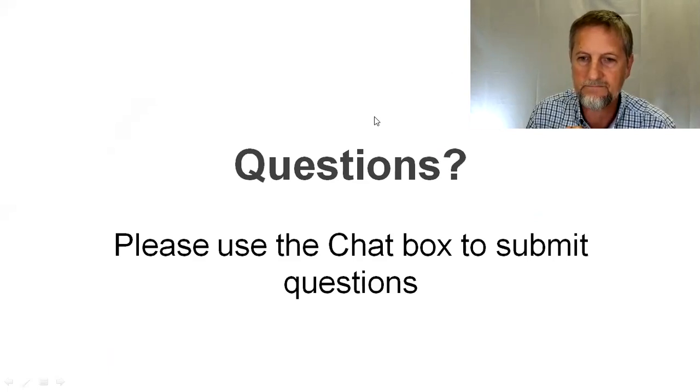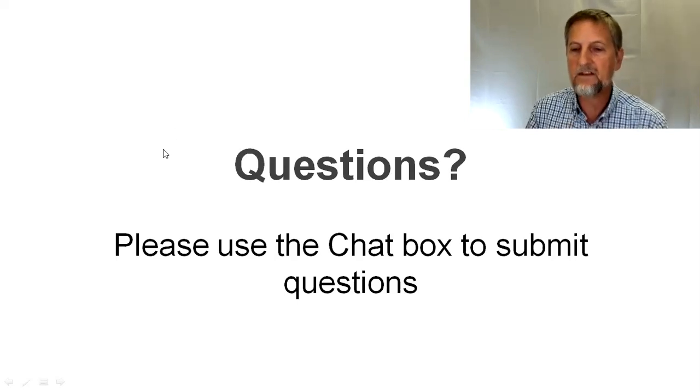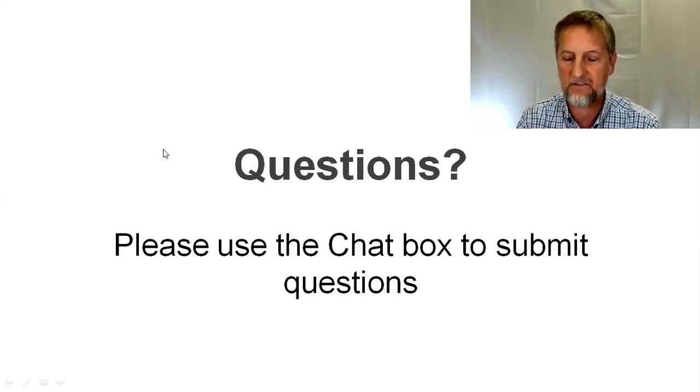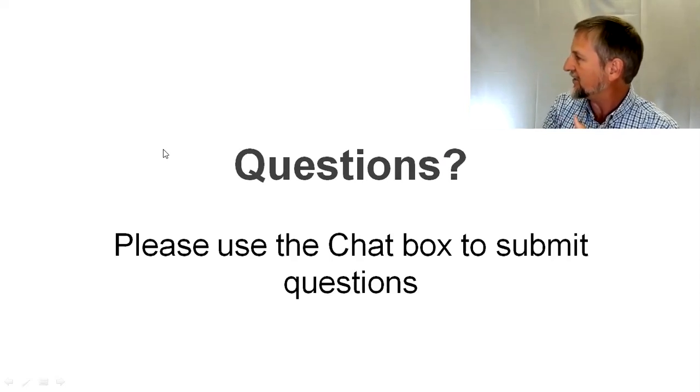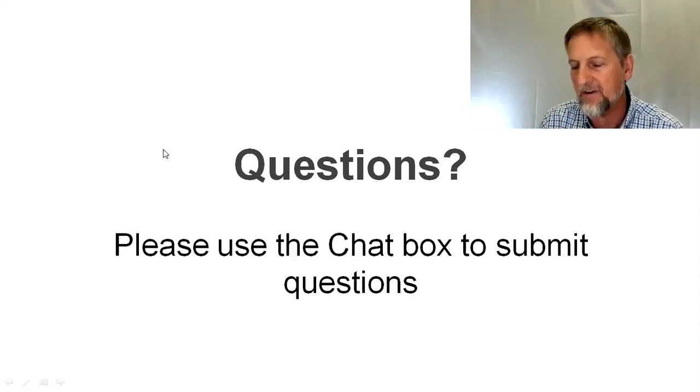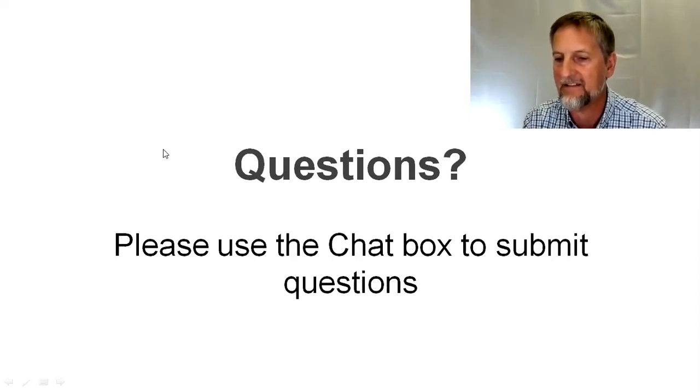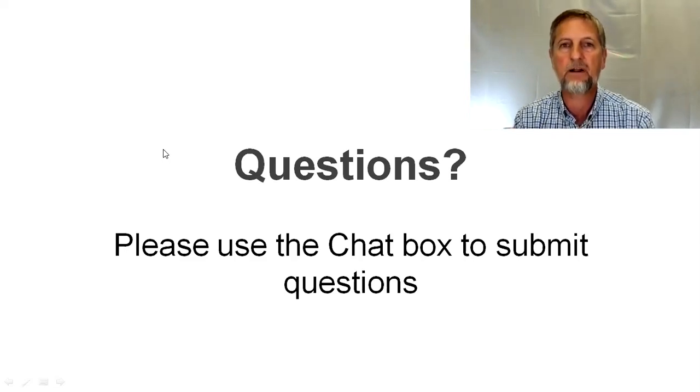The first question is, can GPR or Impact Echo identify the rebar size in foundations? No. GPR can sort of measure rebar size, but it's really not the ideal tool. The best way to measure rebar size is frankly with one of the many rebar locators that are out there that can measure the rebar diameter right at the top.